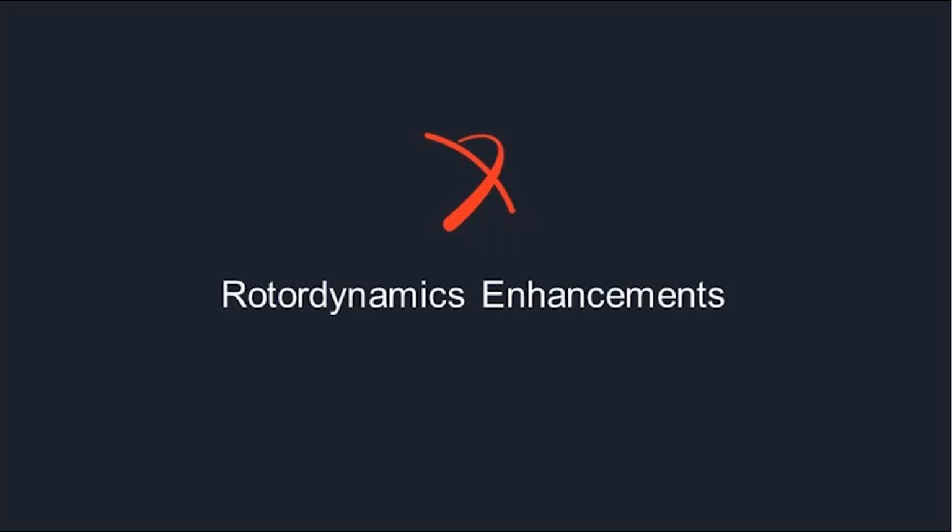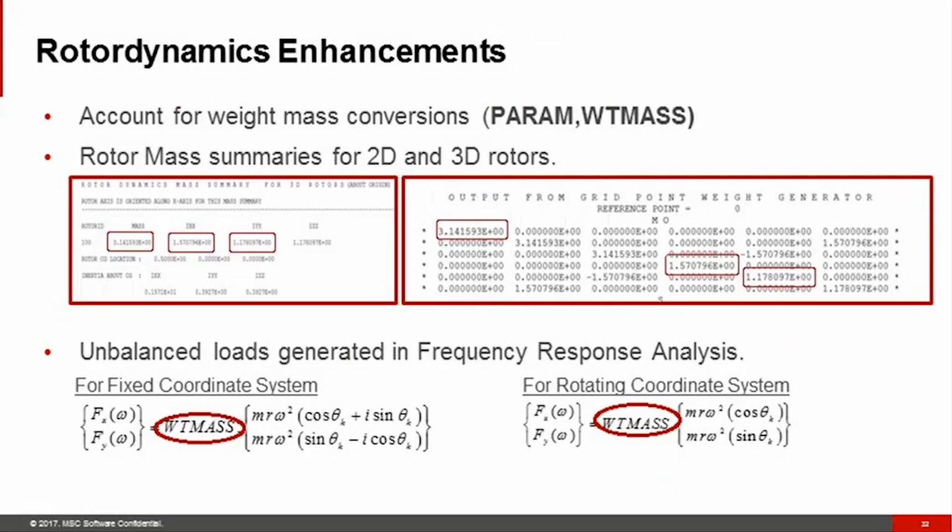Next, I'll be talking about the rotor dynamic enhancements. In Nastran 2018.2, we have made enhancements to account for weight mass in rotor dynamic analysis. Weight mass is the scaling factor between mass and weight, and we're all familiar with that. This parameter was not reflected in rotor mass summaries in previous versions. In 2018.2, this limitation is removed, and now you can see the mass summary for 2D and 3D rotors calculated correctly and scaled by the weight mass parameter. And as you can see here in the slide, the results match the grid point weight generator output.